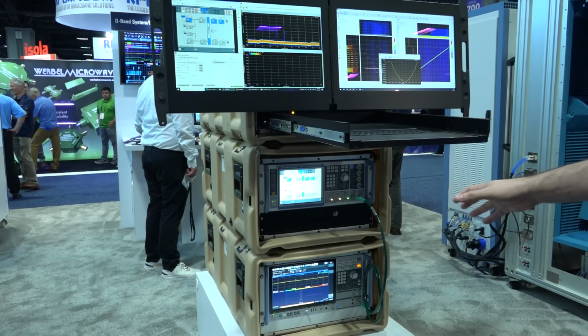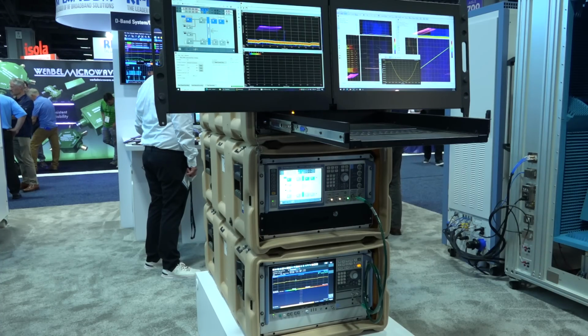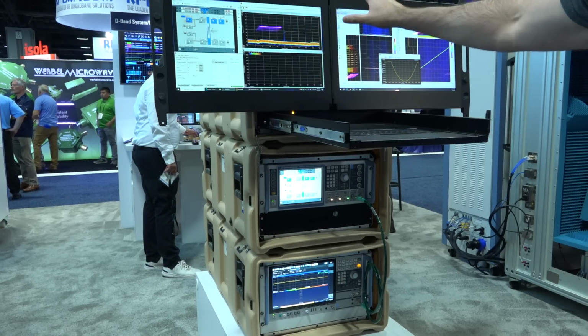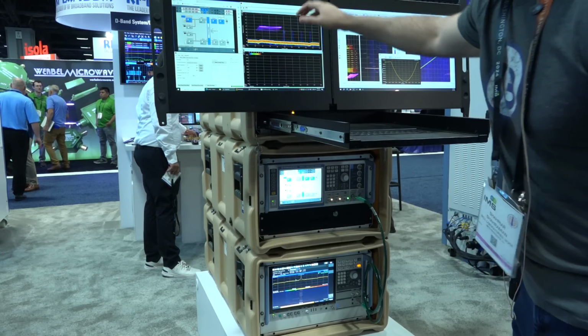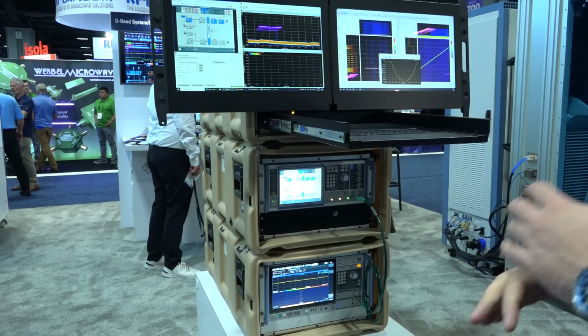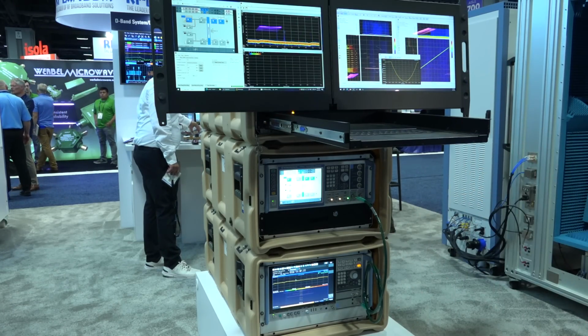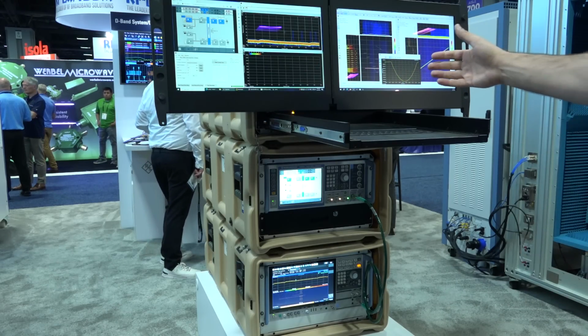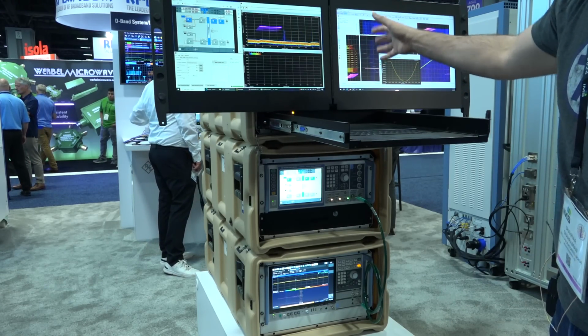So what this is essentially is a mobile, really broadband, really low noise, software-defined radio. There's almost unlimited storage at the top behind the screens. You deploy this in the field, you listen, you capture everything, you IQ stream everything at the highest rate, store it, and then you can pick it up and leave. And then you can analyze all kinds of signals that were present at the time where you actually measured.